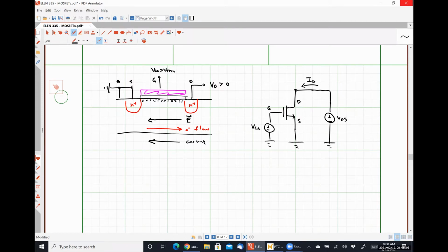The drain technically is the terminal at a higher potential than the source, which is always at a lower potential in an Nmos transistor. It does not remotely matter which one I put at high potential and which one I put at low potential, because it's a 4-terminal device and I can always just tie my body to the one at low potential. The source and the drain are identically doped. They are identical in size. This is a completely and utterly symmetrical device, not like a BJT at all. So for the Nmos transistor, the drain is always at a higher potential than the source, which is why the current flows from the drain to the source, all right?